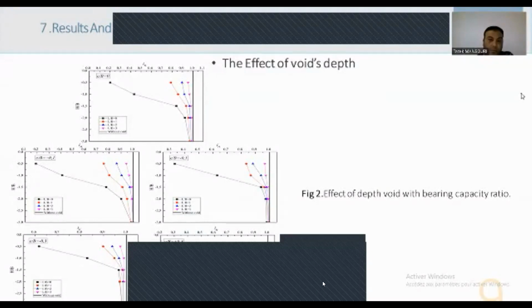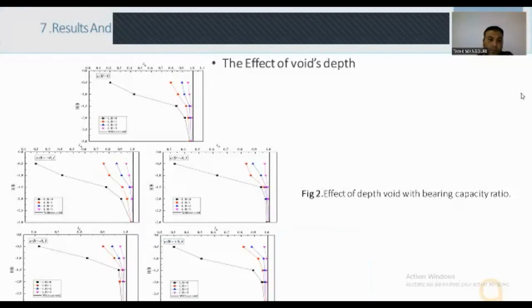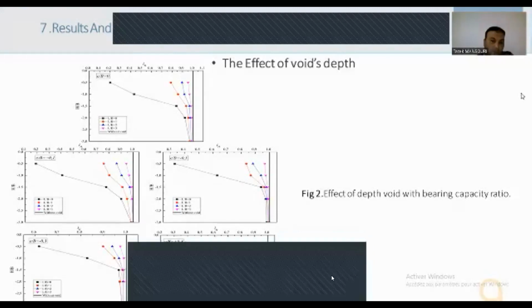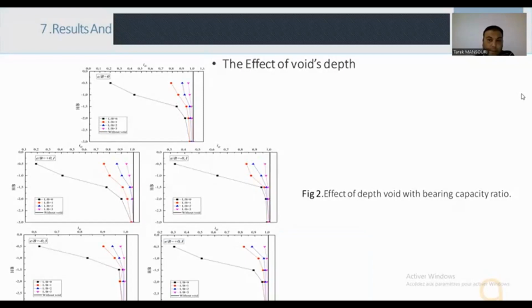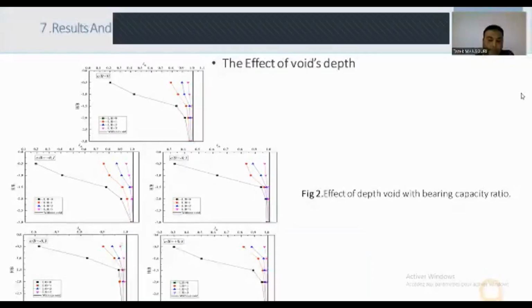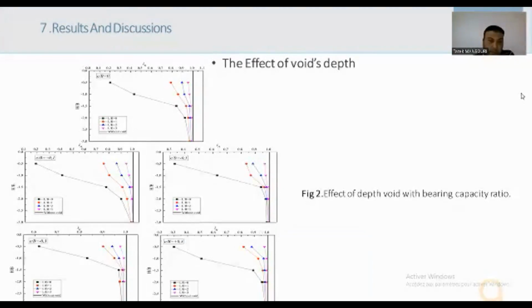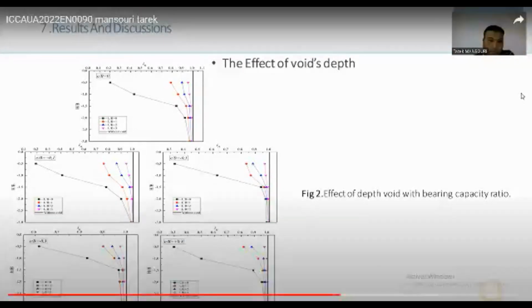Furthermore, in the cases at H/B equals 1 and 1.5, notably, we observed the same impact for negative and positive load eccentricities, but with less significant intensities. Also, a critical depth was reached at H/B equals 2, a similar result to Beatty and Wang, 1984.